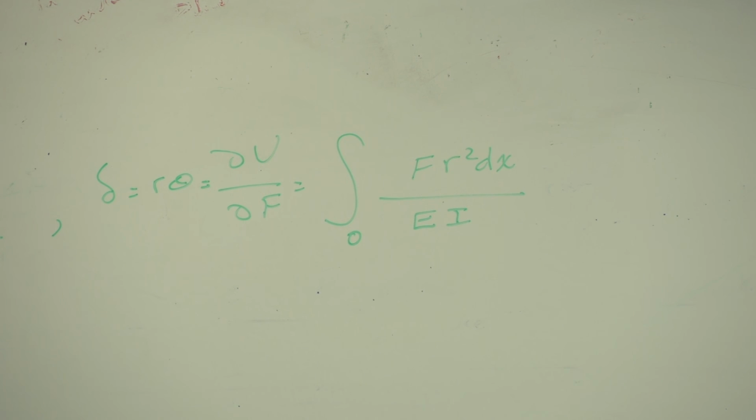The whole spring is under bending, right? Yeah. The whole spring. Therefore, the length should be the length of that spring if you unwind it. Remember, that's how we came up with this equation. It was a straight beam.